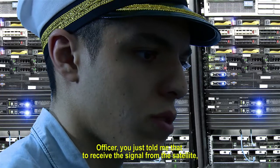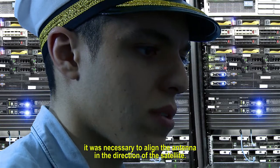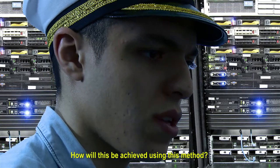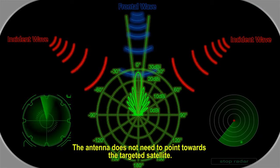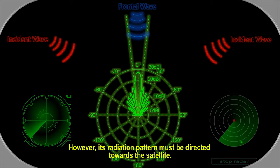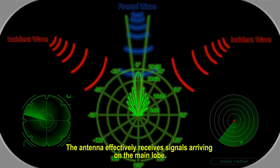Officer, you just told me that to receive the signal from the satellite, it was necessary to align the antenna in the direction of the satellite. How will this be achieved using this method? The antenna does not need to point towards the targeted satellite. However, its radiation pattern must be directed towards the satellite. The antenna effectively receives signals arriving on the main lobe.